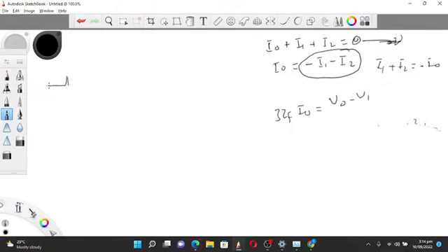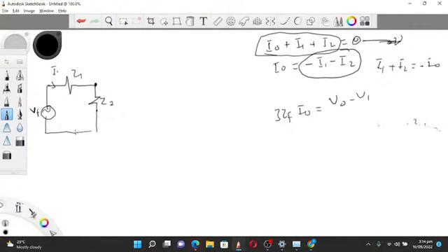So we have I1, since I1 is the positive phase sequence, our VF is here. I1 plus I2 plus I0, the sum should give you 0. That means they are meeting at a common point. So if this is a common point, I can put my Z2 here, this is Z1. I can put my Z2 here, like that, and then I2 will be going this way.